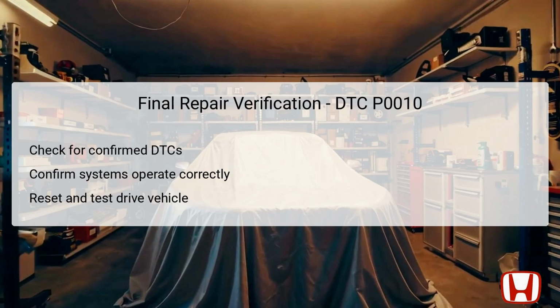Next, ensure that all systems are functioning properly without any abnormal readings. It is also important to reset the vehicle's systems to clear any historical fault codes. Following the reset, a test drive should be conducted to evaluate the vehicle's performance under typical driving conditions, monitoring for any signs of reoccurrence of the DTC or related issues. Successful completion of testing confirms the integrity of repairs made to the VTC oil control solenoid and associated wiring.